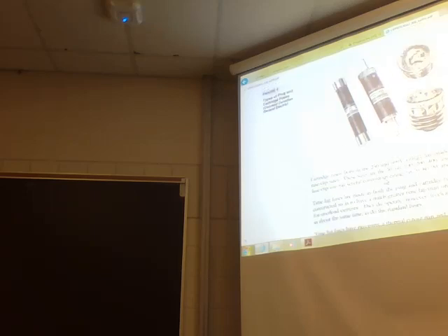Cartridge fuses, both in 250 volt and 600 volt ratings, are made to fit standardized fuse clips. These sizes are 30, 60, 100, 200, 400, and 600 amp sizes. Each fuse clip size has several continuous ratings of 70, 80, 90, 100 amps.